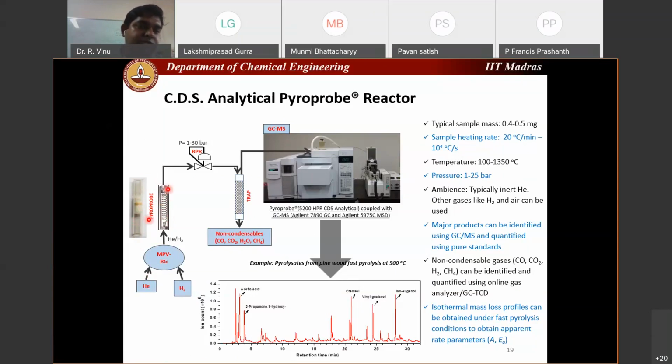Okay, and of course this has high pressure operation and so on. I'm sure the Frontier micropyrolyzer also has a tandem reactor that Karthik mentioned that can do high pressure operations and everything that this system can also perform. So this is how it is. So you have a pyrolyzer unit, and then the vapors are taken through a long 1/16 inch SS tube, a heated transfer line, which is actually not there in a Frontier micropyrolyzer, and that's sometimes an advantage when you can prevent some secondary reactions.